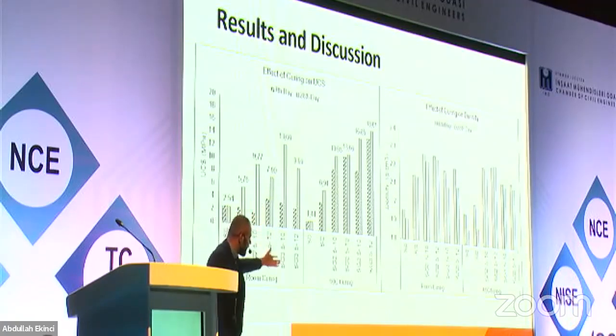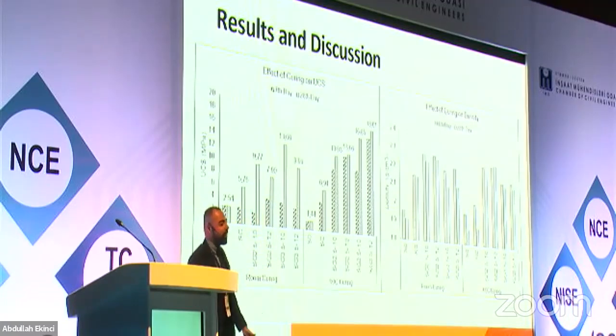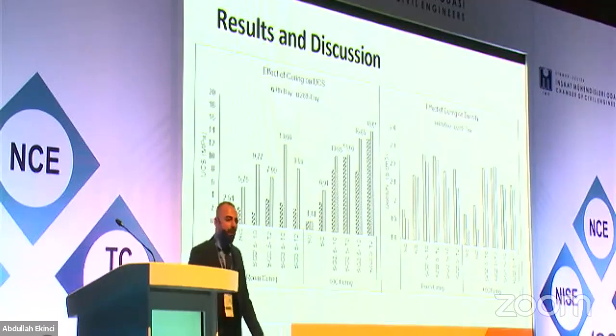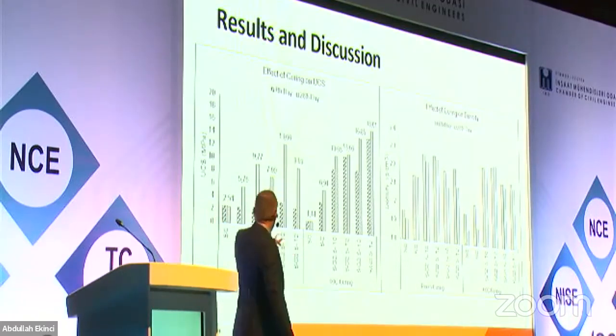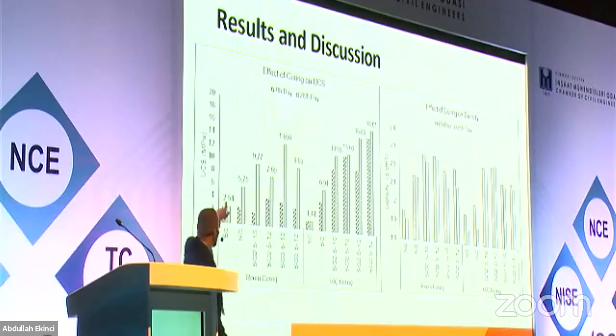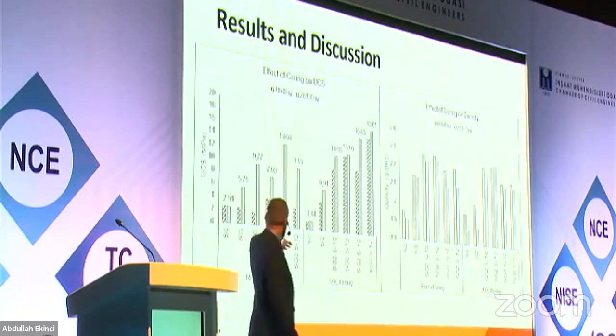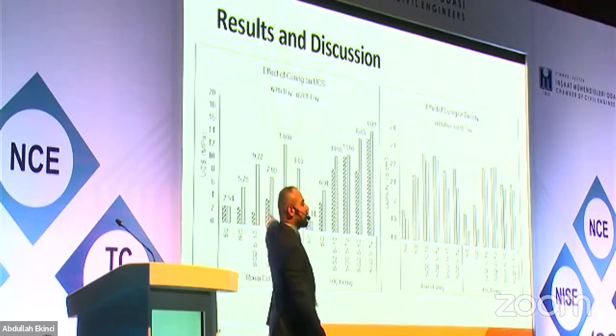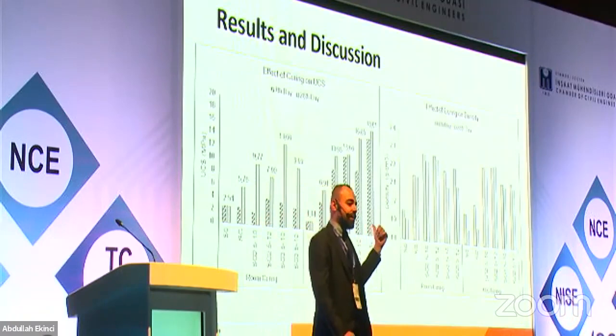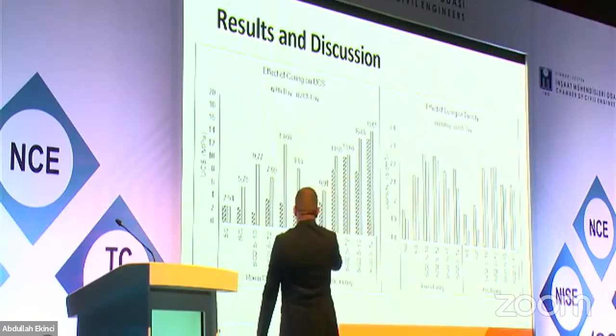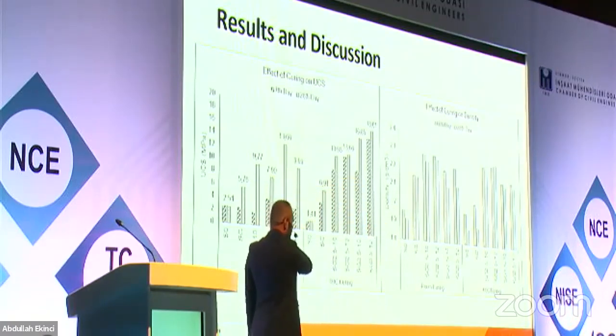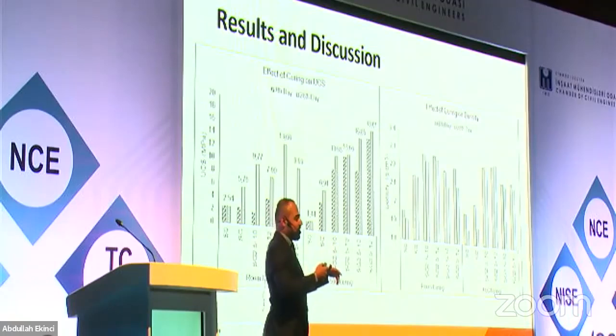But the things that we're interested in here are the strengths that we gained in the process. Well, we can see this is the soil without cement, and we have one control which has 10% cement to compare with the result that we have. Since they are in a dry condition, we have a higher strength. I'm sure that this isn't typical for soil stabilization, you see that this is high strength, but because they are dry, not at optimal moisture content, that's why I have these results here. For the soil, it's 2.54 megapascal, it's high strength basically, because it's a dry state. We left them at room temperature for the 28 days.